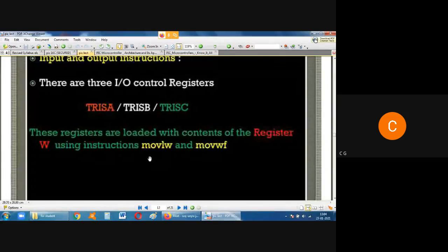But once it reads, it is not necessary that the CPU understands the meaning of the instruction. We write instructions in our language. That instruction goes into the decoder. The decoder converts that instruction into a 0101 string, which switches on and off different flags, registers, transistors, or logic gates, and then it will start manipulating the data, and then it will again store the values into the register.